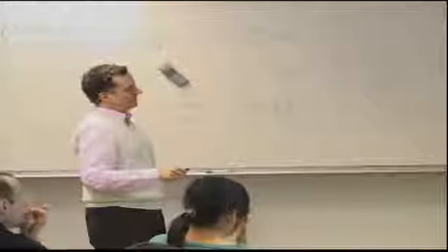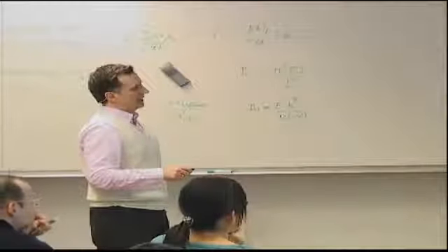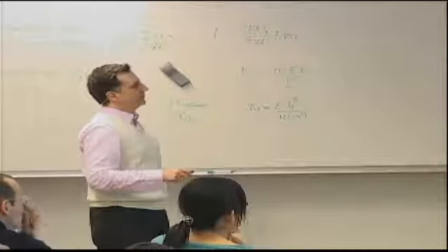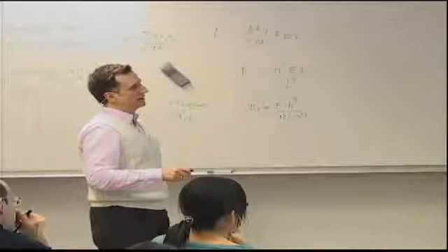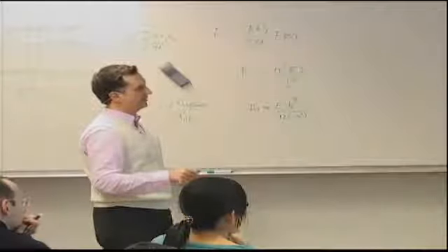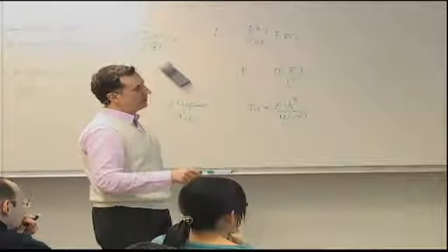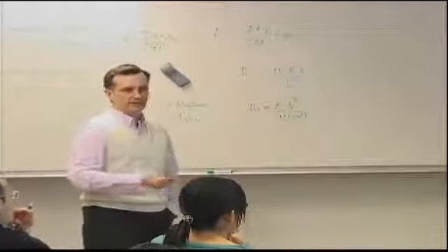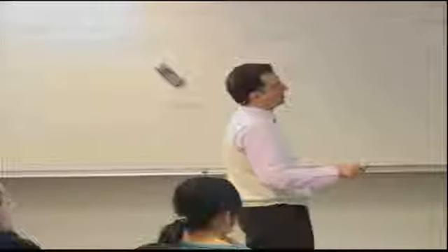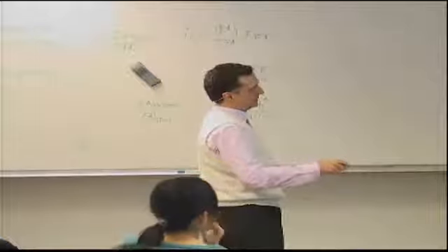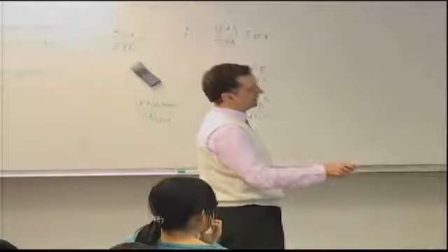The load P reaches a fastener, then some of that load splits and goes into the light blue laminate, and some of it continues on. And in fact, it turns out by symmetry, and because I have only 3 fasteners, you can find that if you call P1 the load that is transmitted right after the first fastener, then P minus P1 is the load that's left, and then that P minus P1 hits the next fastener, which will have to transmit back to a P minus P1 here and a P1 there, such that you maintain the anti-symmetry of the structure here.